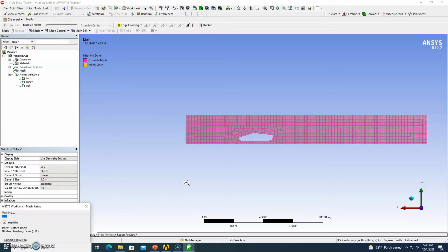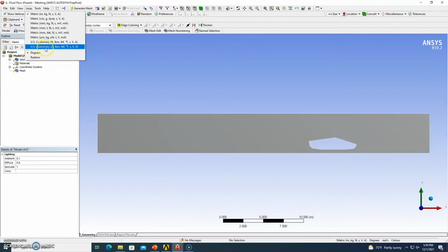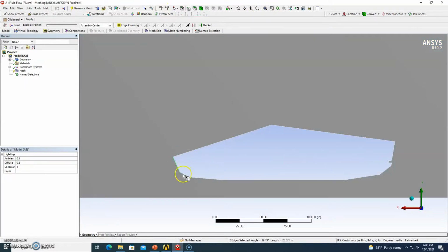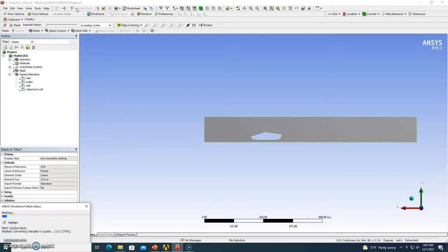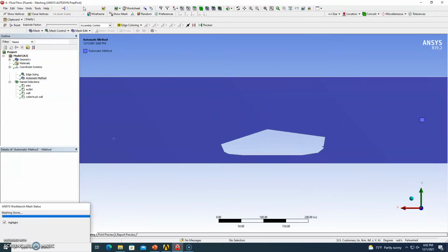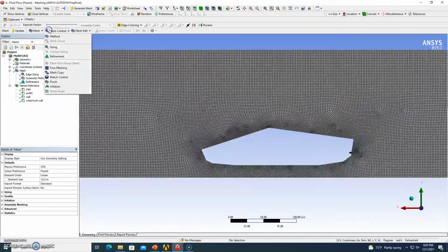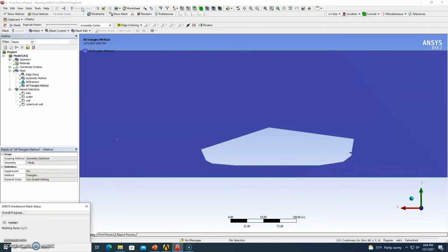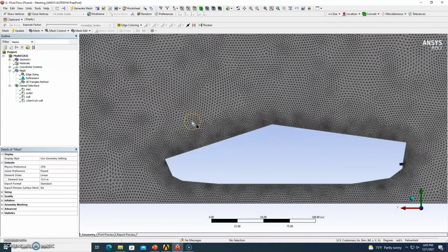Our final mesh was constructed in Design Modeler. At the front, you can see we have 2 Cybertruck lengths, and at the back, we have 5 Cybertruck lengths. At the top, we have at least 1 additional Cybertruck height in order to correctly display all of the contours that we need. As mentioned before, we used sizing and refinement to further decrease the size of the cells around the Cybertruck in order to increase the accuracy of the simulation. As we zoom in here, we can see the very fine cells around the Cybertruck that will be used as areas of interest in the calculation.